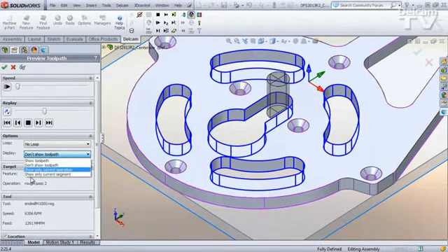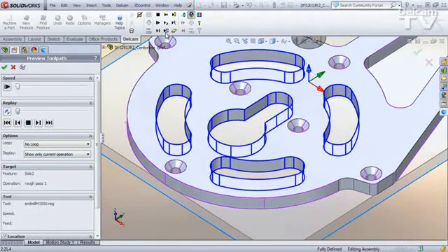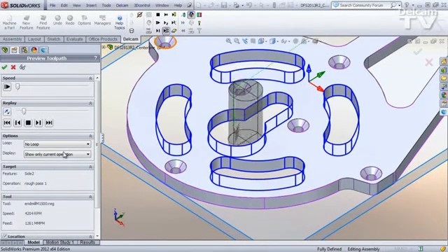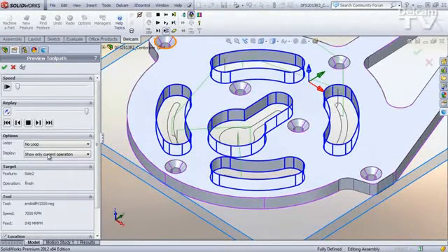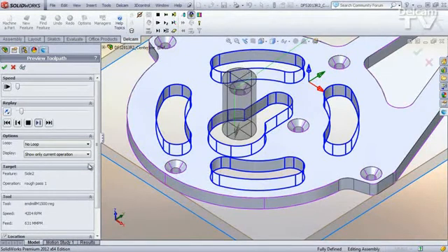Okay, so that's not showing the toolpath at all. I can show only the current operation. In that case, remember we have 2 roughs and a finish. So I'll play one operation at a time. We still have these controls up here too. So I'll play the first rough, and the toolpath disappears. Here's the second rough, and when it finishes, again the toolpath disappears, and here's finish. So if you're single blocking that, when you get to the end of that operation, that toolpath will disappear.